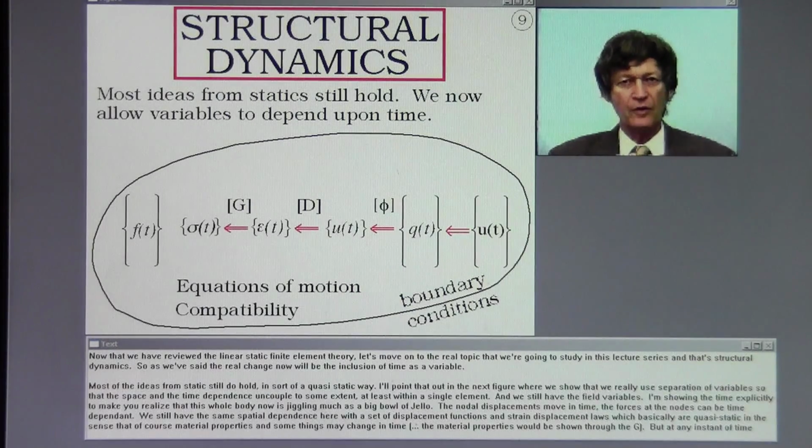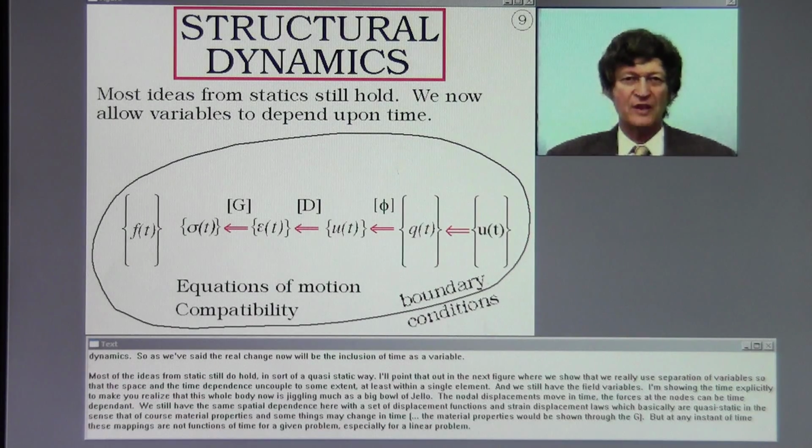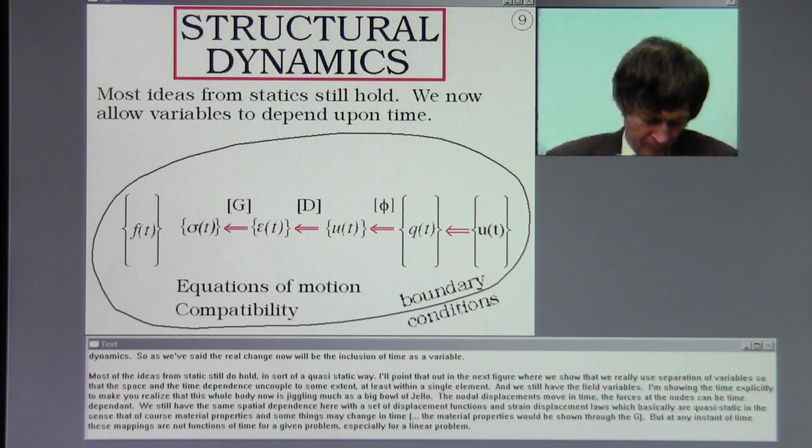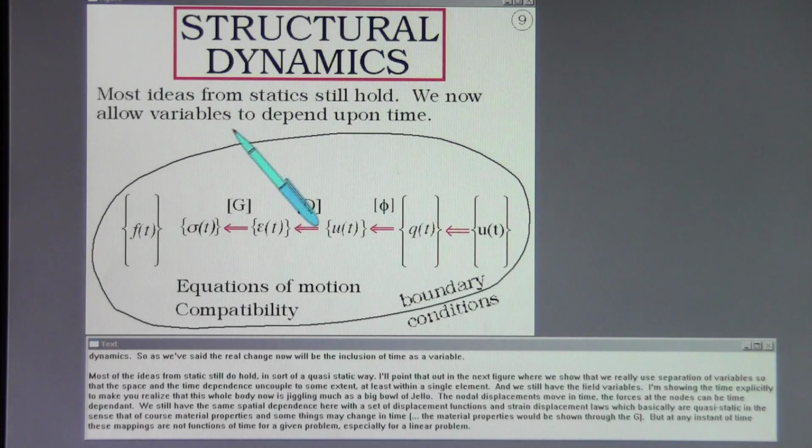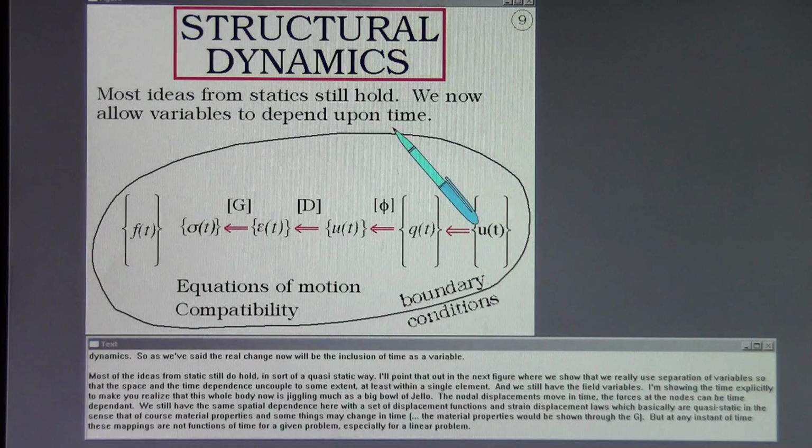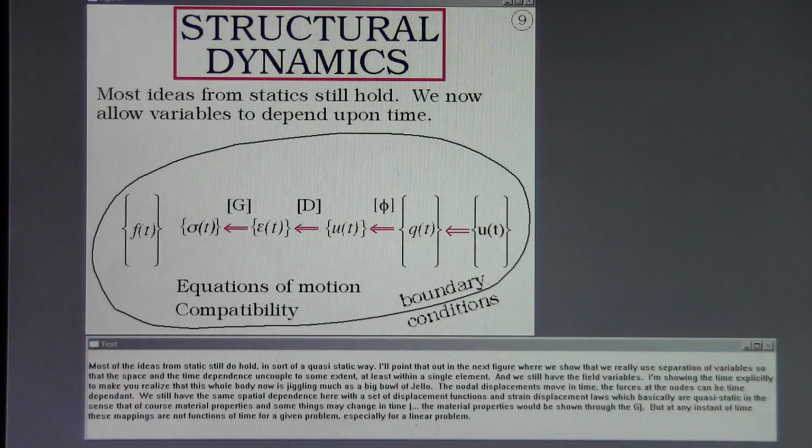Now that we have reviewed the linear static finite element theory, let's move on to the real topic that we're going to study in this lecture series, and that's structural dynamics. So as we've said, the real change now will be the inclusion of time as a variable. Most of the ideas from statics still do hold in sort of a quasi-static way. I'll point that out in the next figure, where we show that we really use separation of variables so that the space and the time dependence uncouple to some extent, at least within a single element.